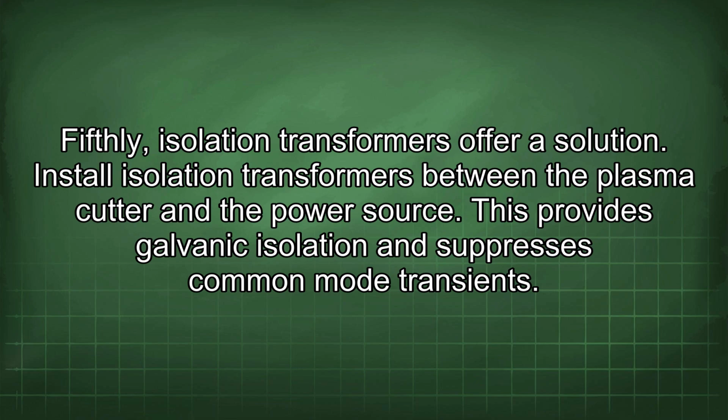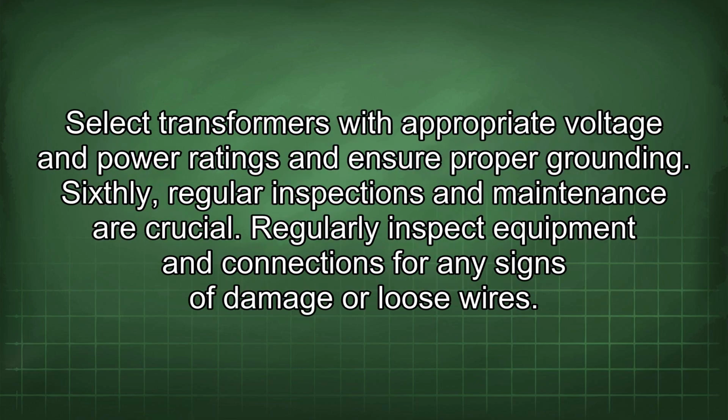Fifthly, isolation transformers offer a solution. Install isolation transformers between the plasma cutter and the power source. This provides galvanic isolation and suppresses common mode transients. Select transformers with appropriate voltage and power ratings and ensure proper grounding.